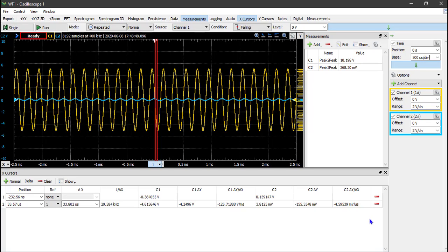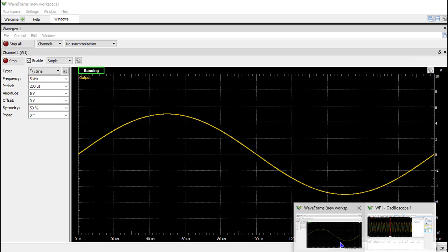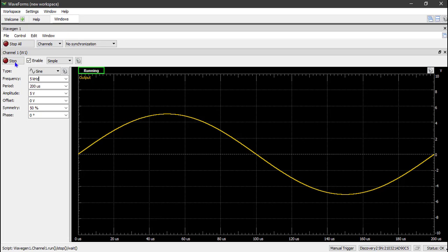Something that you should keep in mind is that in this lab, there really aren't any issues in terms of noise or in terms of the output not being consistent with pre-lab calculations with theoretical results. So if for some reason your measurements are way off or are exhibiting different trends than expected based on theory, that means that probably something went wrong. It's not just an error of noise or something like that. So then I would double check your circuit, and I would double check that you're specifying the right waveform in the WaveGen. In any case, this concludes the in-lab portion of Lab 1.